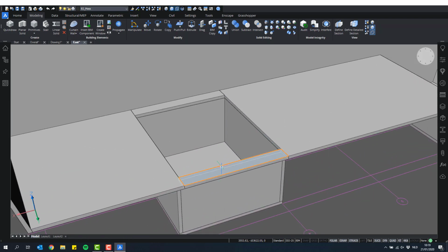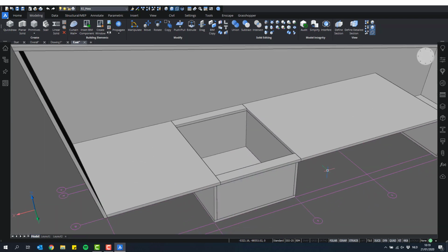And I can see here also the split tool made too many splits actually. We want to have these 4 solids union, so I'm going to union and click this solid, this, and this, and press Enter. So now this is one solid.